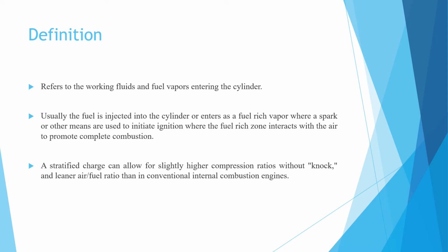Therefore, there is a need to develop an engine which combines the advantages of both gasoline and diesel engine. At the same time, it should avoid as far as possible their disadvantages. Stratified engine is an attempt in this direction.